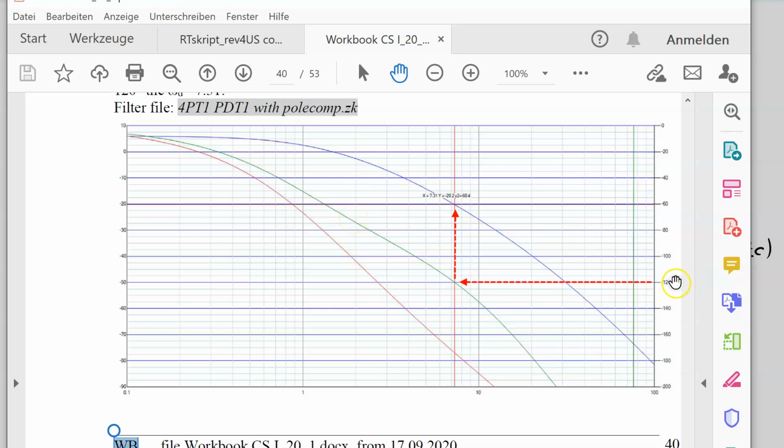And at once you can see, with the same phase margin value, this is minus 120. So up to minus 180 we have 60 degree phase margin. This distance, 60 degrees phase margin. This was a P controller phase margin, omega D value 2.6.